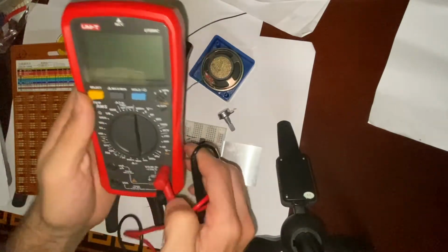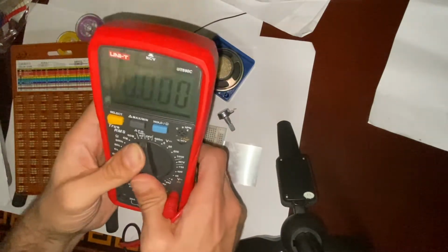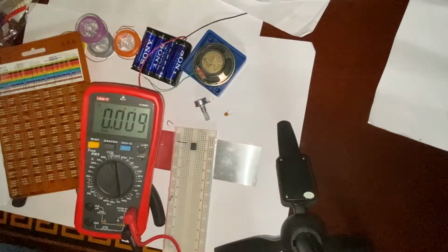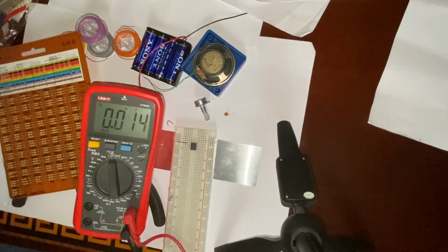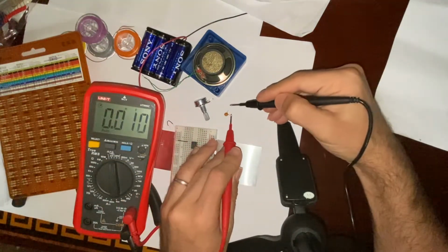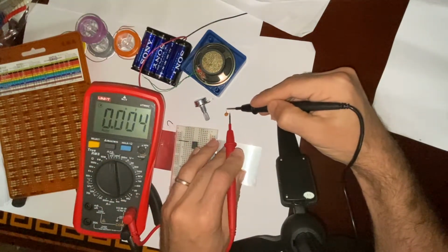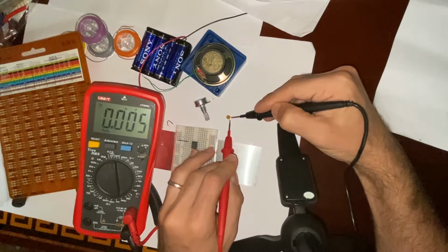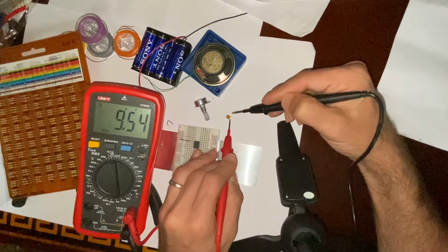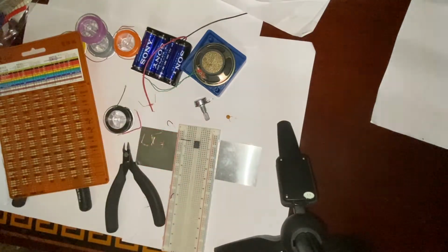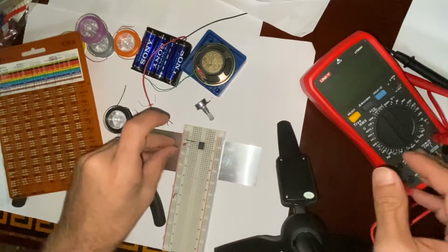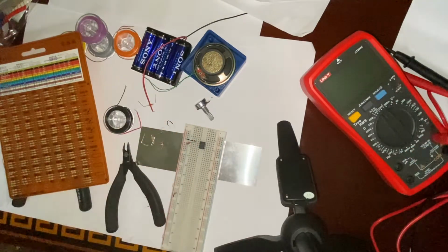I use it on the F of farads, and we have a little bit of an issue. We need to take it out of the circuit to be able to measure it. The test leads by themselves, the cables, they already have capacitance. You can see the number is oscillating somewhere in the 10 picofarad. And I try not to touch with my fingers just because it will alter the measurement. And I see that it's 9.5 nanofarads, very close to 10 nanofarads. So when I place it, I'm sure that I chose the right one.